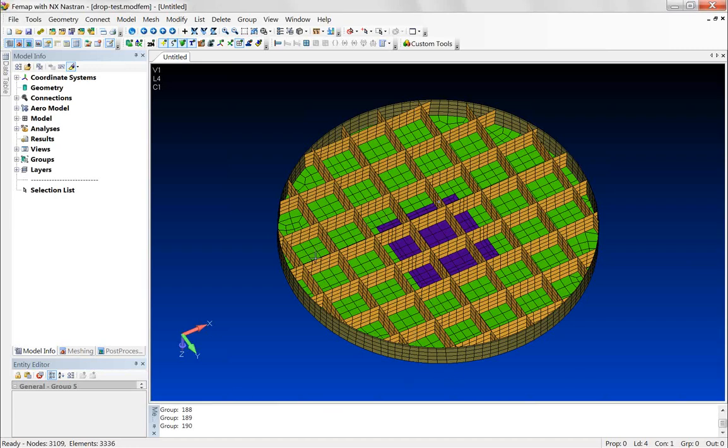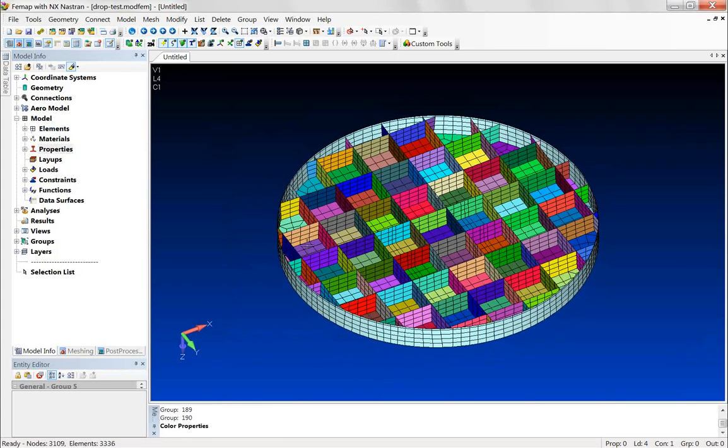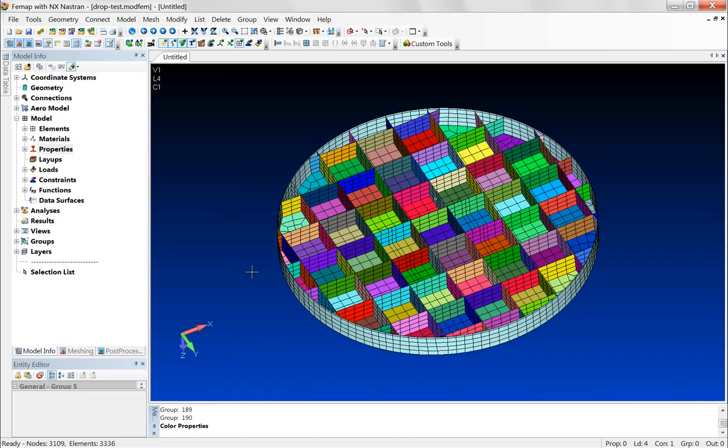it's made each of these different webs, it's assigned the elements of each of these webs into a new property. To be able to better visualize this, I'm going to randomize the color of these webs. And you can see that, wow, I've got a lot more properties than I did before. And I didn't have to go into any property creation menu to do that.